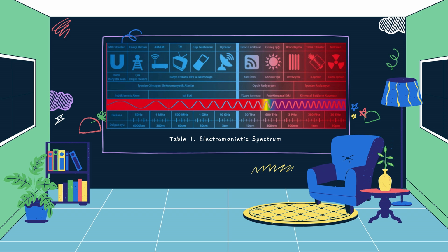1. Electromagnetic spectrum, the address of drone signals. All radio waves are part of the electromagnetic spectrum. Drones typically operate on 2.4 GHz or 915 MHz frequencies. 2.4 GHz, higher data rate, but shorter range. 915 MHz, longer range, but lower data rate. Wavelength-frequency relationship. For example, at 2.4 GHz, the wavelength is about 12.5 centimeters. This directly affects antenna size and signal propagation.